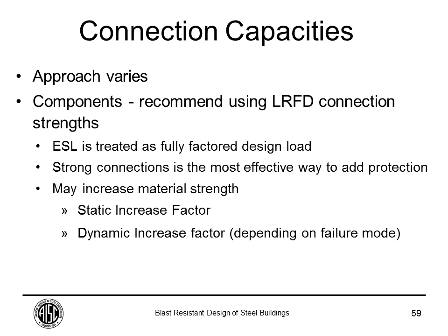Again, the approach varies. I've seen specifications that allow the use of 1 as your phi factor. Some other ones require the phi factors. Some may actually tell you not to use any increased factors in your material strengths and to design using the lower bound strengths. The typical recommendation that we make is that you design for your equivalent static load, and you use that load as a fully factored design load.